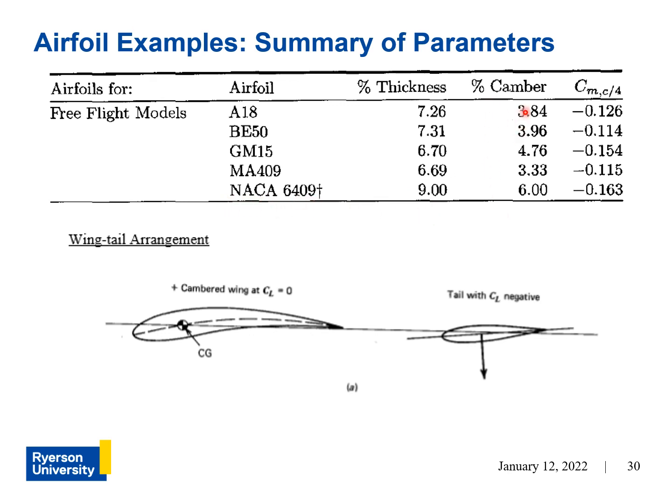You can also see the camber of each, and that affects the performance of the airfoil. And another parameter that we haven't seen is the pitching moment about the aerodynamic center. Here you can see that they're negative values, implying that each of these airfoils on their own will cause a negative pitching moment, so they have a tendency to pitch down, right?